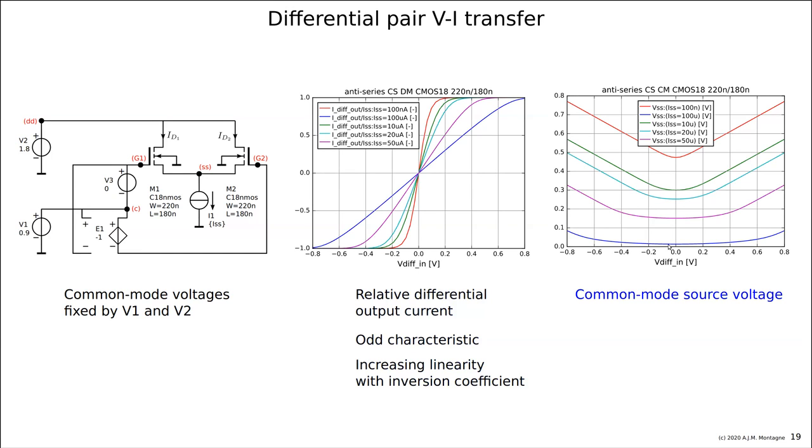But if the voltage becomes larger and one device is fully conducting and one device is fully off, then you see the even characteristic of this thing. And then you can really see it, of course, in the red one. You could call this a rectifier. It's an even function. So the common mode voltage here is an even function, while the differential mode quantities are odd, the common mode quantities are even. That's important to know. That happens in balanced circuits. So even characteristic we have here.